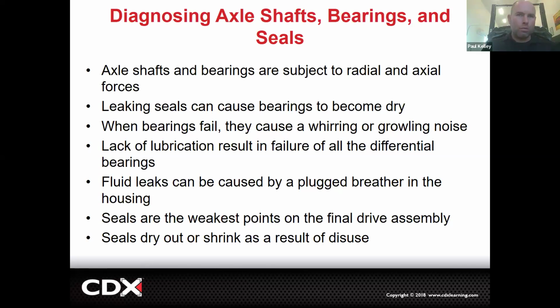But if it's a woo and you can change the pitch, just like tipping your gas pedal a little bit, accelerator, like woo, then I'd more be like, hey, that sounds like a pinion bearing. When you're loading the pinion more or less, that's going to change the pinion bearing because you're putting more load on it or less load on it, right? That would be kind of some bearing diagnosis.